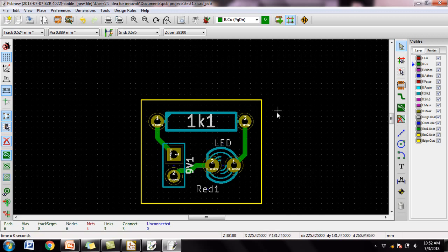After this you will see a PCB. When you see a PCB, it is covered with copper layers around it, with a gap given for the tracks. That is, a ground plane will be added around, a ground mask for the complete circuit. You can add that using the fill zone technique. So use add fill zone.